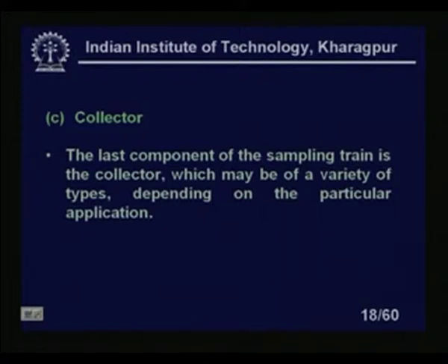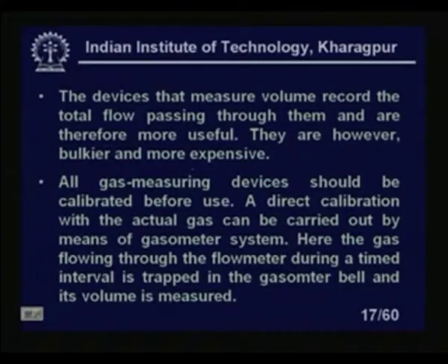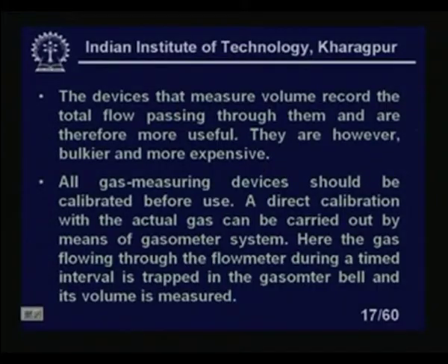So, these are very important considerations. Basically, if you look at the gasometer, the basic principle is that it is a device of known volume. A direct calibration with the actual gas can be carried out by means of the gasometer system, where the gas flowing to the flow meter is trapped in the gasometer bell and its volume is measured.